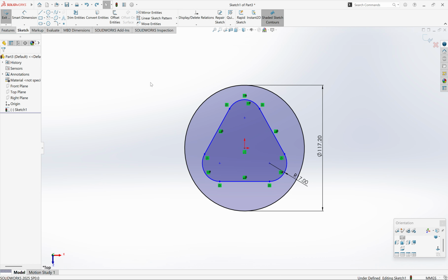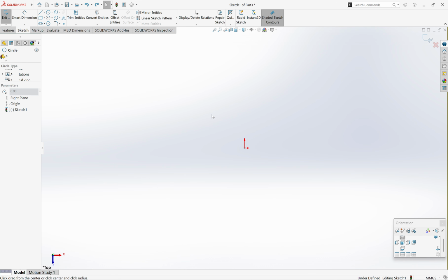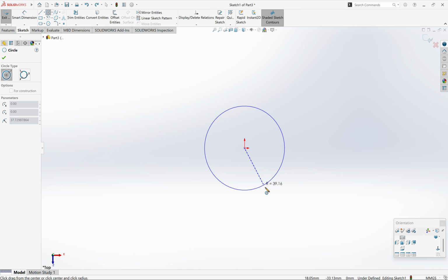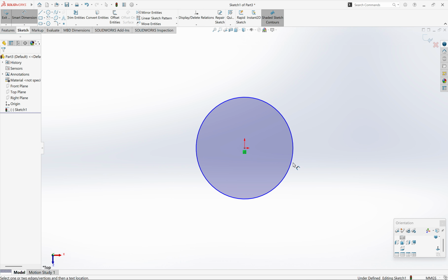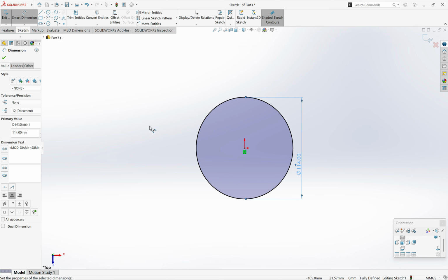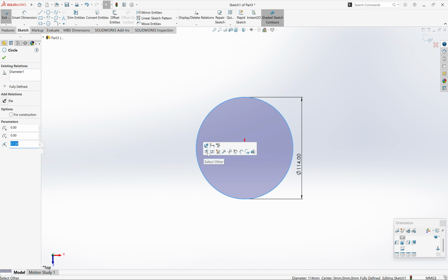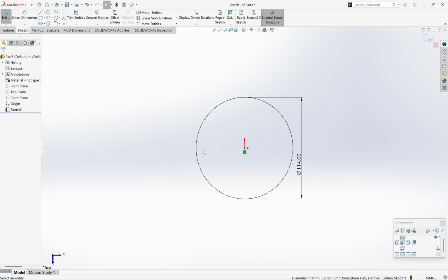We could do something else, which is just get the circle tool, and then from the first do it as 114, then change it to a construction. From here, click on it, and then construction geometry, then get the polygon.